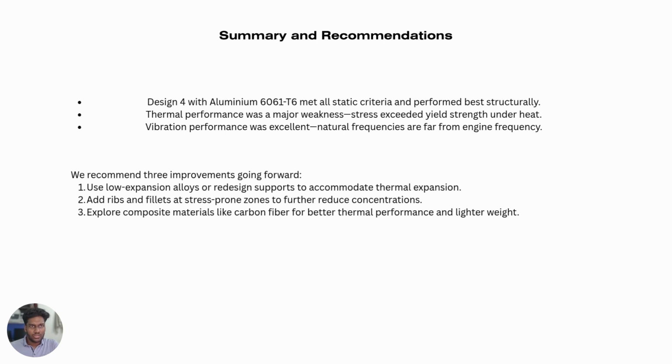So for the recommendations, we recommend 3 improvements going forward. Use a low expansion alloy or redesign supports to accommodate thermal expansion. Add ribs or fillets at stress-prone zones to further reduce concentrations. Explore composite materials like carbon fiber for better thermal performance and lightweight.